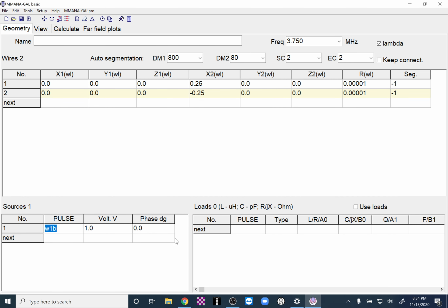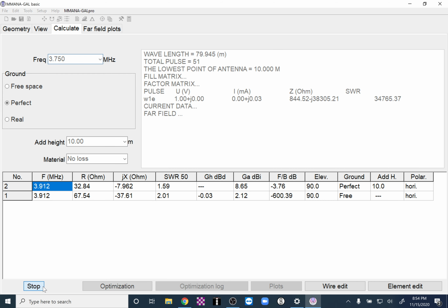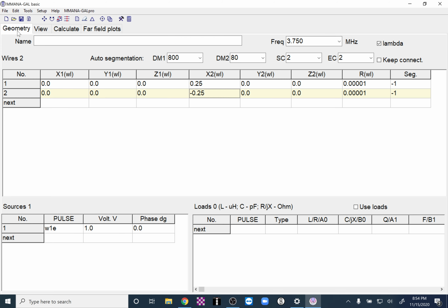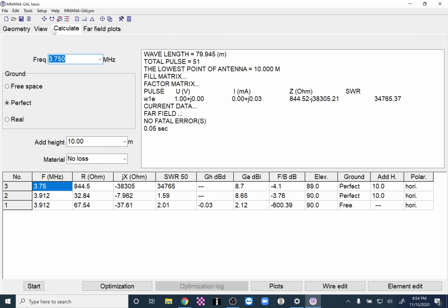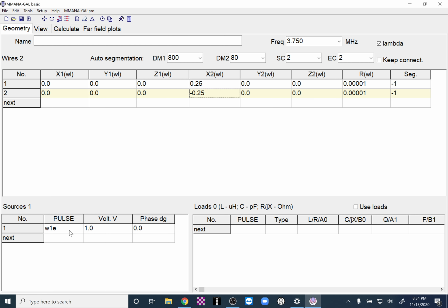You could also do wire 1 end, which moves our feed point to the end of this. If we throw the analyze on this, obviously our SWR is extremely high because it's assuming a 50 ohm impedance match, and at the end of a half wavelength dipole, if you're going to end feed it, you're going to need some type of matching network or something. You could also do wire 2.